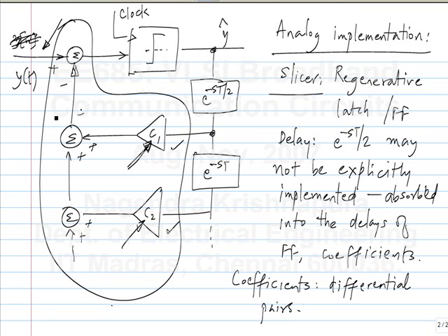Okay. So the equalizer is supposed to provide high frequency boost and compensate the channel. It will also have to compensate for all the bandwidth limitations that you introduced in your circuit. Okay. So if you have a low pass filter in your circuit, it will have to boost it up to compensate for that also, because any low pass filter, whether it's the channel or your circuit, will introduce intersymbol interference. Okay. So clearly in high speed circuits, the key is to minimize all parasitic capacitances so that you don't introduce any bandwidth limitation. It's hard enough to equalize the channels. You don't want to make your job even harder than that.